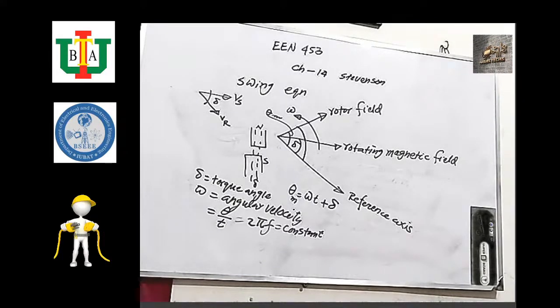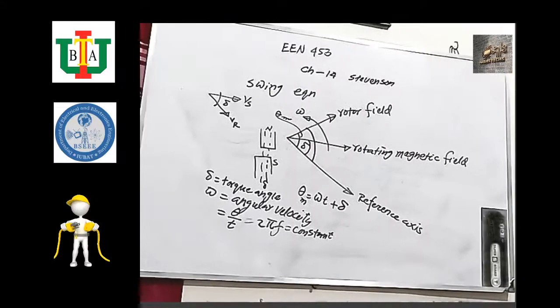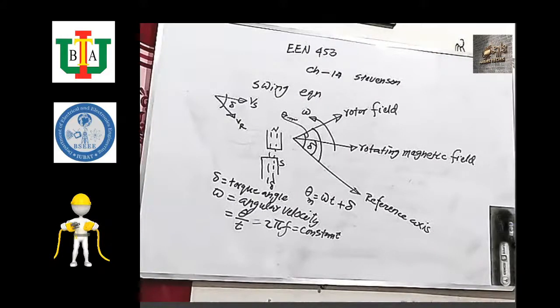Sir, what is the I cos theta controller? I hear this name. What does it mean? I cos theta is the active component of the current. There are many types of control. I cos theta is the active current controller. It only controls the I cos theta component of the current, and I sin theta is the reactive component of the current.